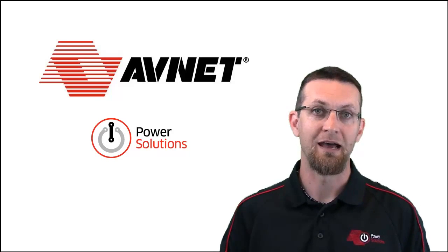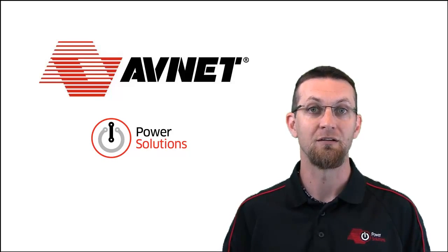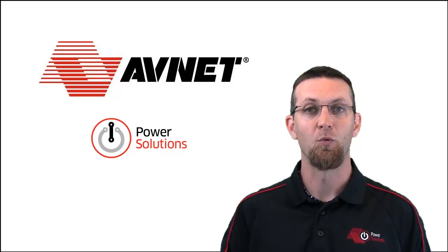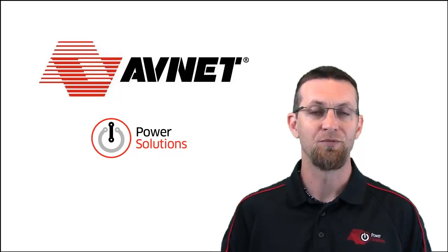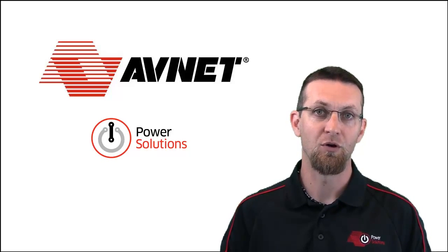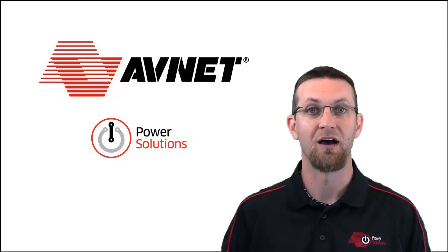With that in mind, Avnet has worked with several of our power manufacturing partners to try to develop a series of reference designs to help get you started on your transceiver architecture design. Now, as is the case with so many things on an FPGA, it's not a one-size-fits-all type of solution. You have to do a little upfront work to figure out exactly what your specific power needs are going to be. In this video, we're going to go through some of the steps in defining your power architecture requirements and then where you can get information to help you design to those specifications.